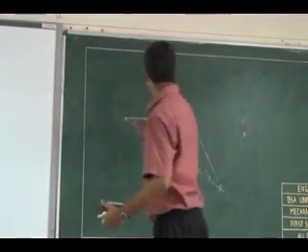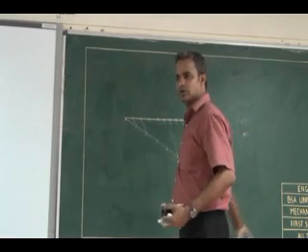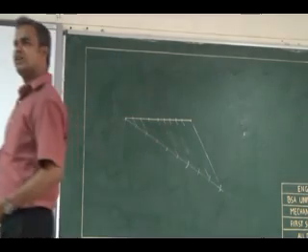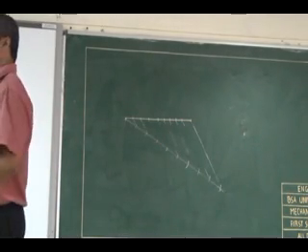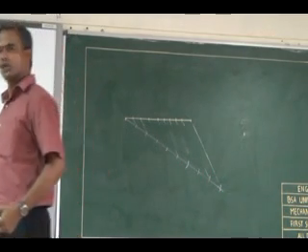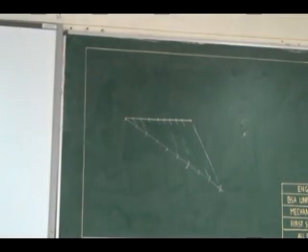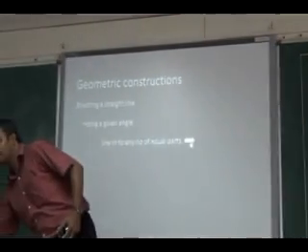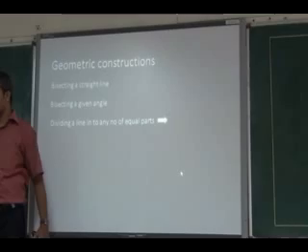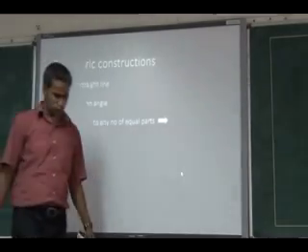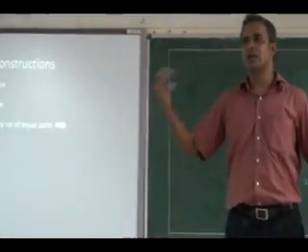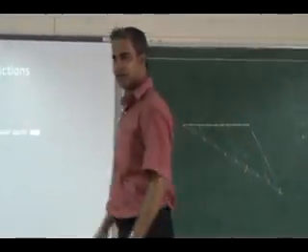Our intention is just I have to divide my line into 9 equal parts. Right, these are all the construction work. Okay, that should be very light. So whatever portion you are able to avoid, you can avoid it in your construction work. Now, you see how I can use my drafter for dividing a line into any equal number of parts. So we have some other geometry constructions. We'll continue that in the later lecture.